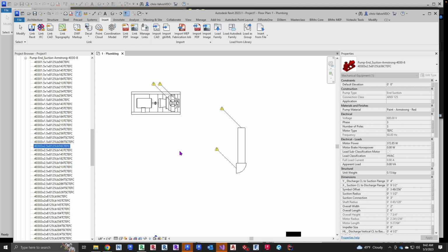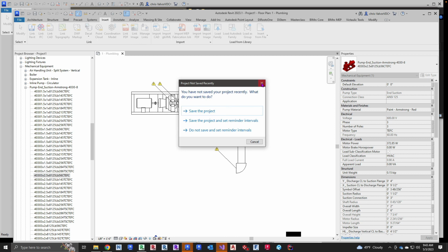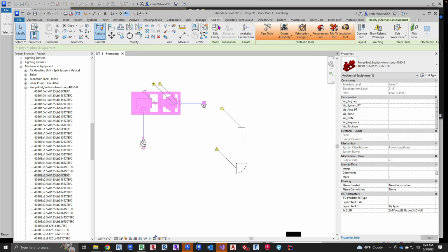Okay. Anything created after 2013, you're an idiot if you had lookup tables off to the side. Unless, I don't want to say idiot, because sometimes you want to make your families lightweight for one size versus another, but just embed the damn lookup tables and let your people go through.